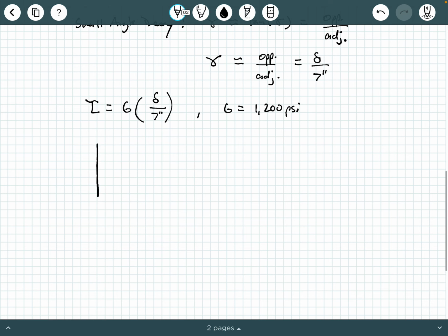Here's our cross-section area, and of course it has a thickness of 1.5 inches and a depth of 6 inches, and this is the area that is being sheared, okay? So this is our shear area.